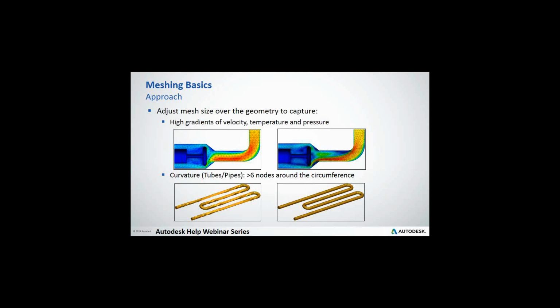And once you capture the geometry, I mean, really, if you're not capturing the geometry, you might as well not run the model. But once you capture the geometry and run the model, you might want to do the refinement of the mesh to really see if you're actually capturing the physics of what is going on.